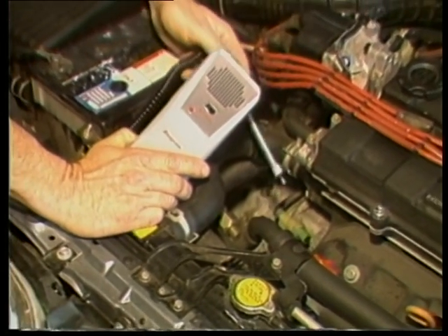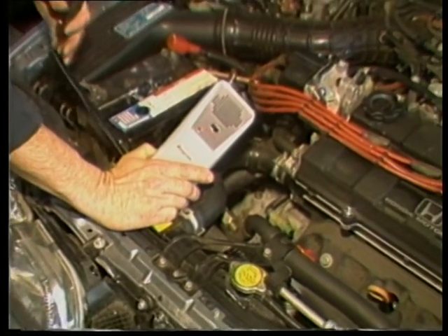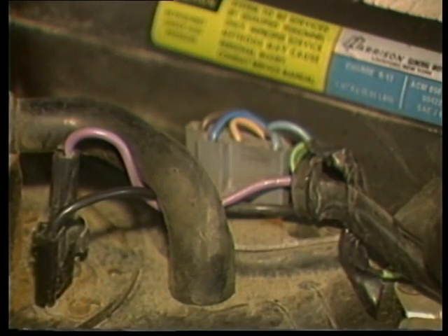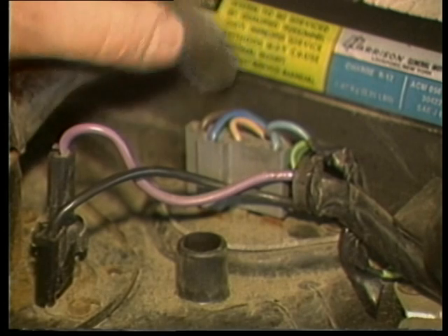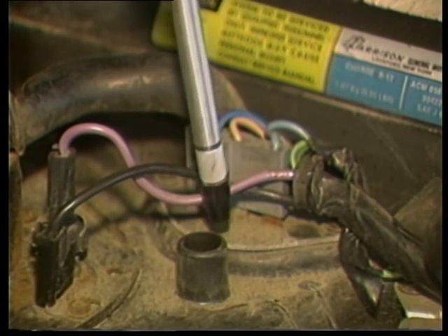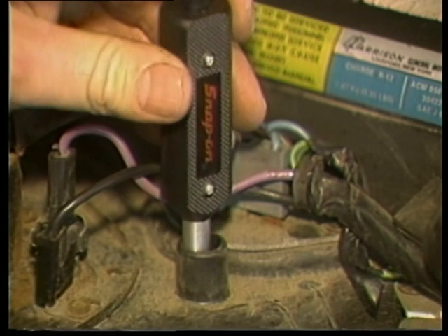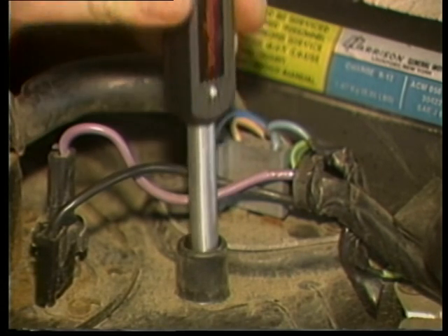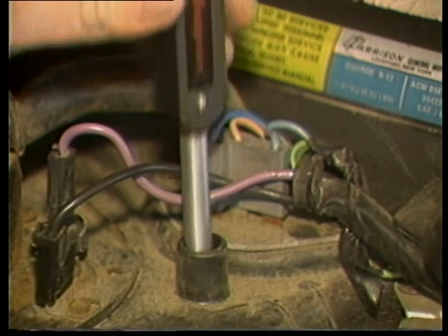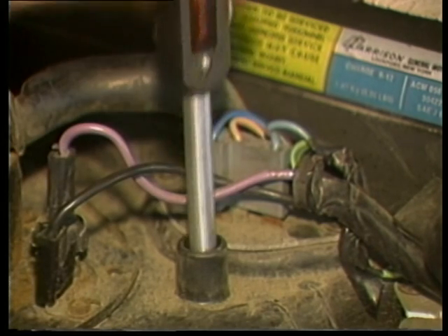The evaporator is another common source of leakage. To check it, insert the probe into the evaporator housing. You can insert the probe as shown or next to one of the low pressure lines. Here we have found a small evaporator leak that would require replacement. You can also find evaporator leaks by testing at the vents in the passenger compartment.